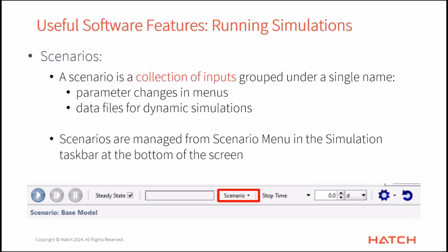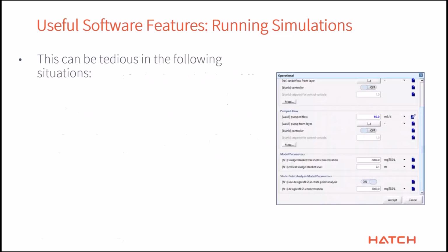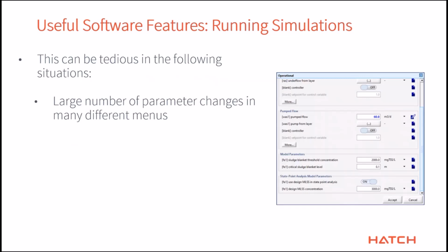So some of our introductory tutorials, if you're doing GPSX tutorials for the first time, you will get a chance to use the scenarios. I'll be honest, though, it's kind of one of those things where it isn't until you do your first project or until you're starting to run a lot of simulations where you realize the real value of doing this. If we did not have this, it would actually be really quite tedious because you would end up having to go to a number of different menus every time you wanted to switch to a new scenario. You'd have to go and make all of those changes. You'd have to probably go back to modeling mode and then rebuild it again and so on.